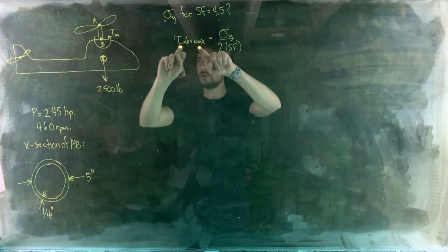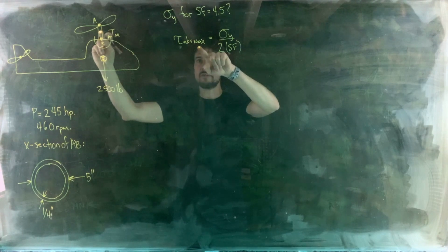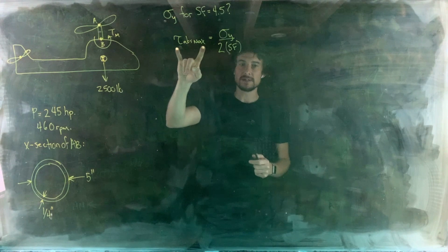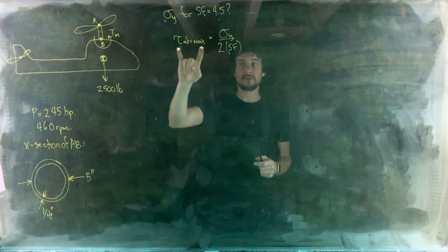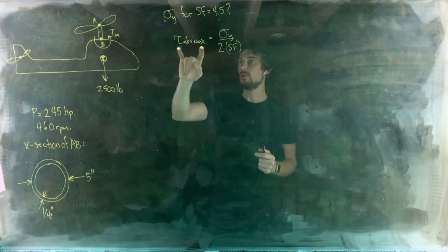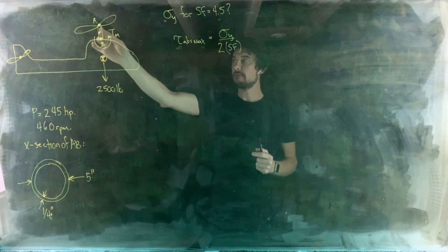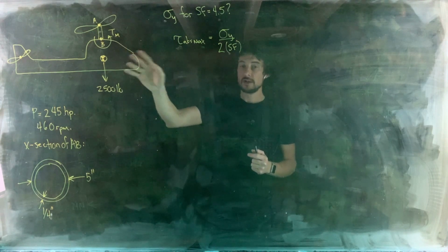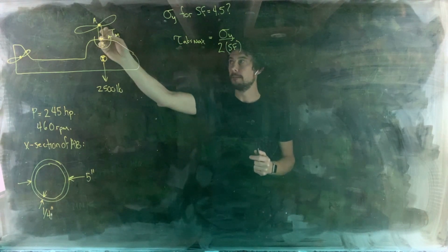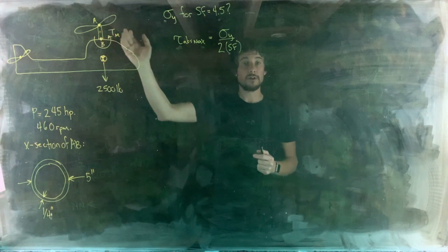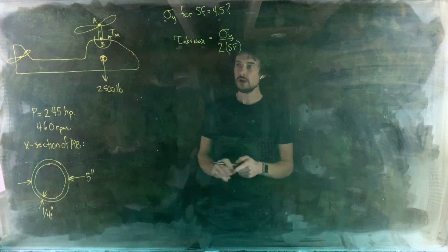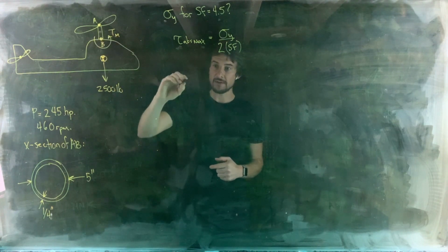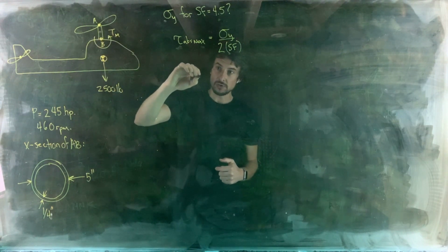The only thing that we need is in that rotor shaft, what is the value of the absolute maximum shear stress? The absolute maximum shear stress comes from Mohr's circle. And the way you want to go about finding that for an object is starting by just considering drawing Mohr's circle for the point in your object that is under the greatest stress. So let's look at a free body diagram of rotor shaft AB to start with.